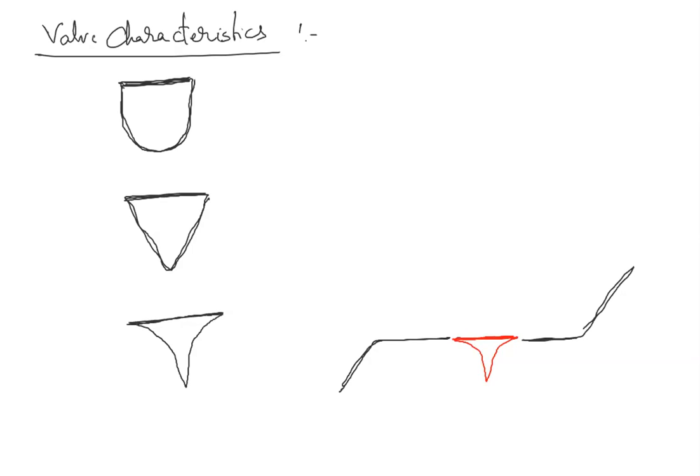This is closed. Suppose you lift the valve by a little bit of percentage. Then most of the clearance has come. This is the clearance where it is flowing. Now by lifting it further, let's say I lifted only 20%, then the clearance has come almost 90% clear. By opening the rest of the 80%, you are going to get only 10%.